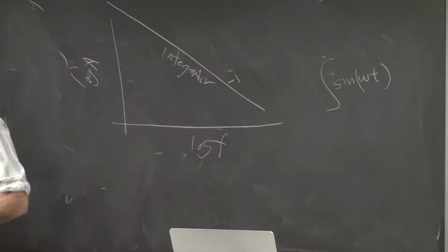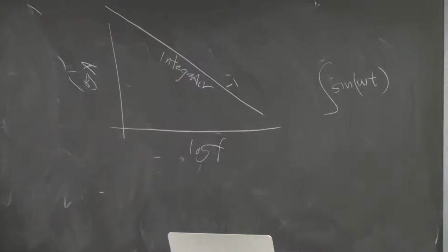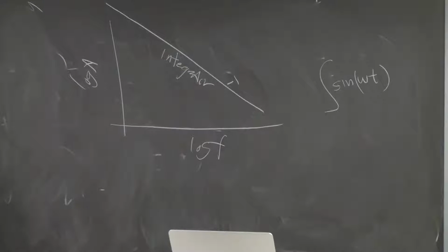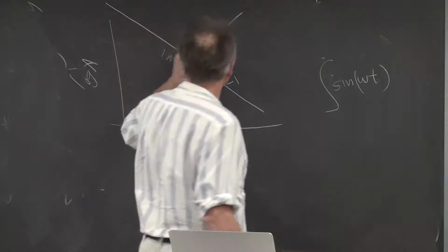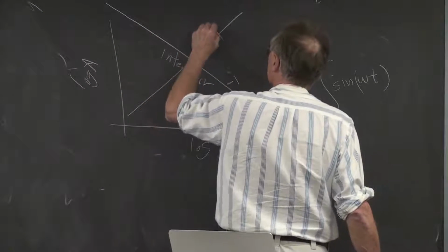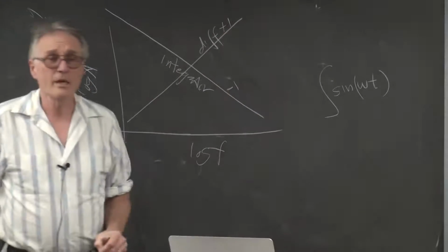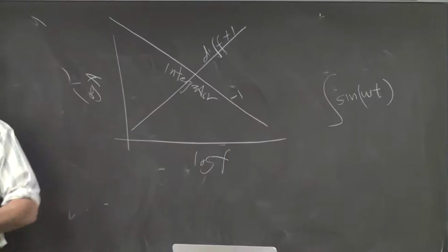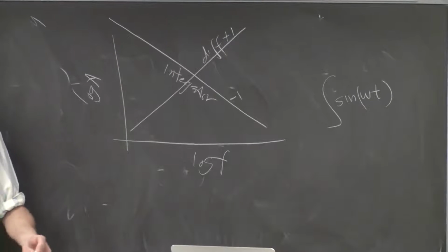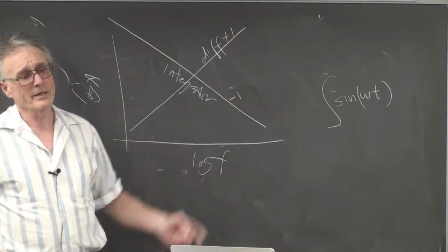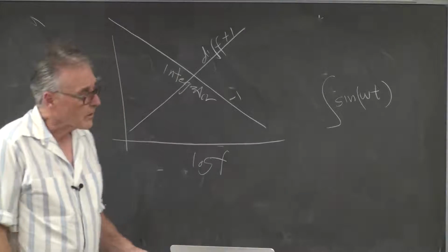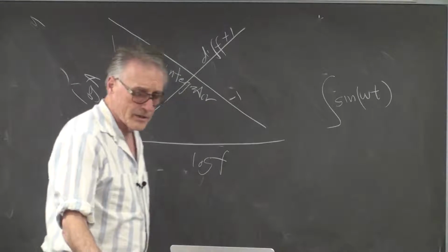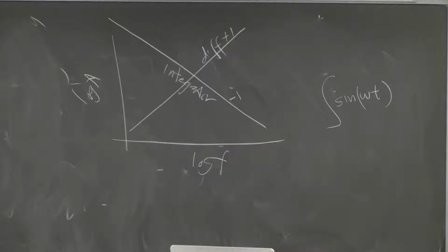Therefore, what must an ideal differentiator be? I saw the appropriate gesture. So the differentiator then is going to have a slope of +1, because as you go to higher and higher frequency, the slope gets larger and larger until at infinite frequency you have infinite slope. So the gain's got to go up with a slope of +1. Okay, enough on Bode plots then. To sort of warm your brain up, let's just solve a motor.